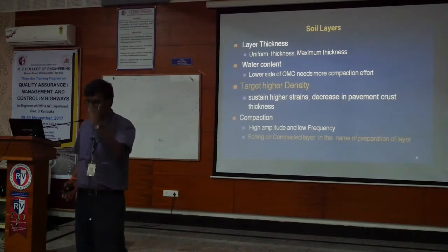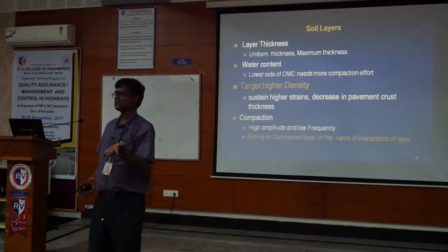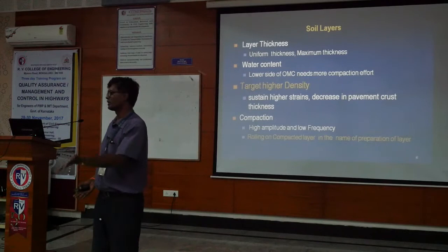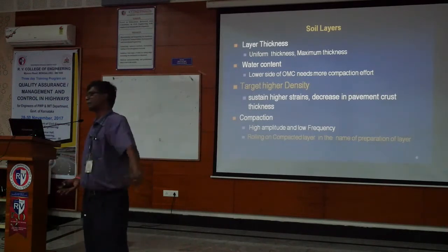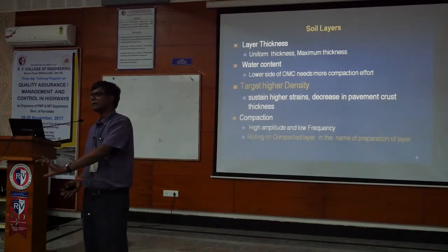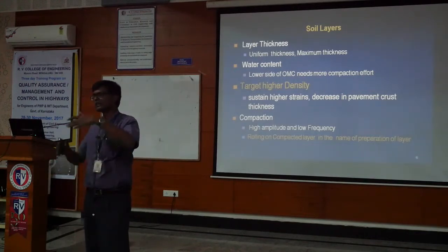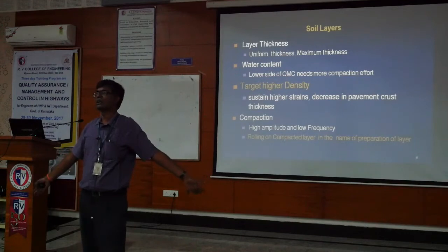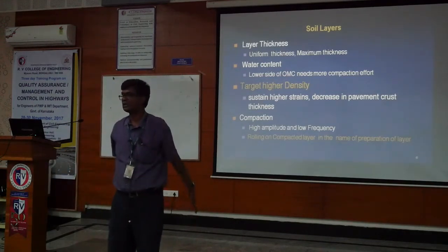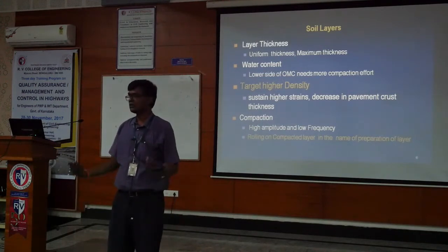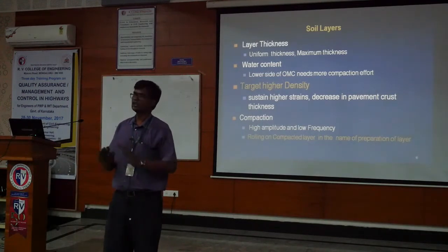It's not a 100% target, but if I can add one extra pass and make 100%, then certainly that should be the target. After all, this is the foundation, and all the stress comes on this and again gets distributed from there. So this should be strong, and the entire stability of the pavement structure is given by this foundation. So that should be the highest.